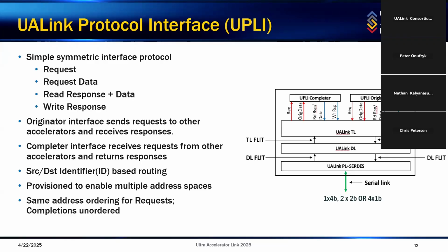The UALink protocol uses AES-256 GCM, hence encryption is organized as three independent streams: a request stream, a read response stream, and a write response stream. Packets within a stream must stay ordered from a source to a destination.